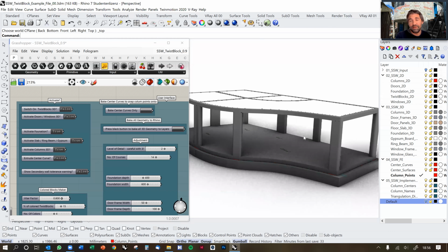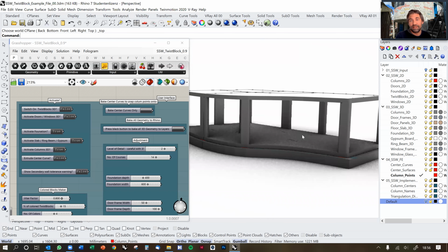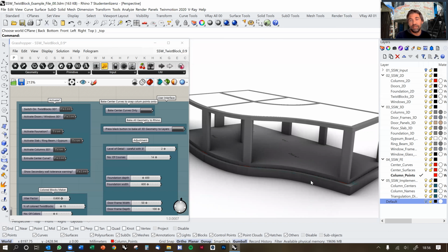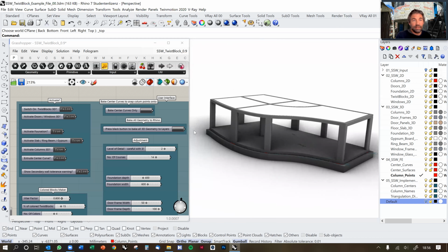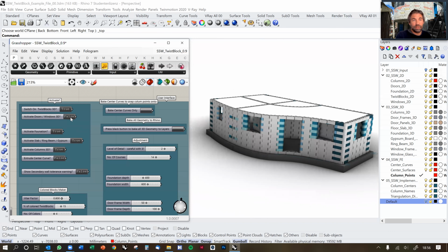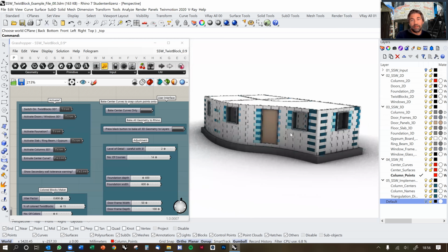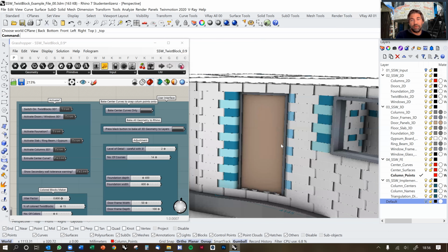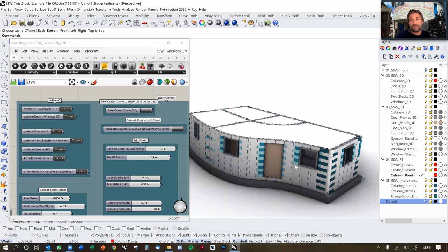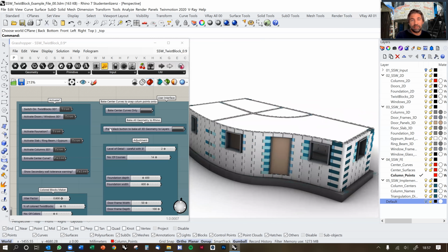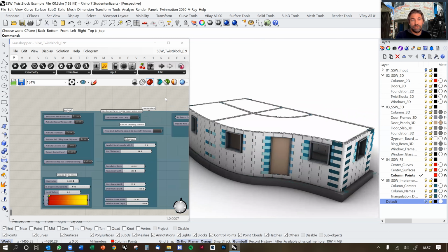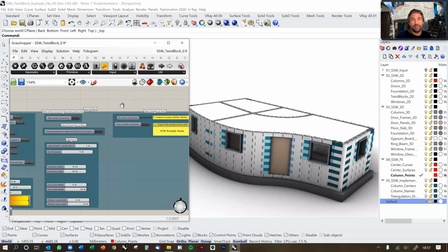Well, okay, this is a heavy earthquake situation, where we need all that stiffening, we need the ring beam, we need the strong foundation, we have the floor slab on the inside. So now we can go back to switching on the twist blocks, and we can switch back on our doors and windows, and now we can say, basically, except from the steel, our structure is complete, and we can do another little tweak, which is quite handy.